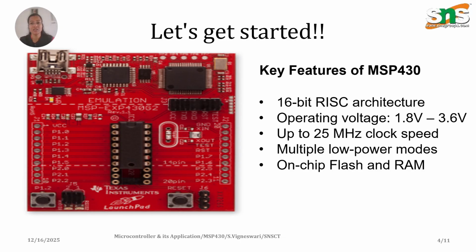The key features: it uses a 16-bit RISC architecture, which means the instructions are simple and efficient. Second, it operates at very low voltage, that is from 1.8 to 3.6 volts, which directly reduces the power consumption. It also supports clock speeds up to 25 MHz, multiple low power modes, and has on-chip flash and RAM.